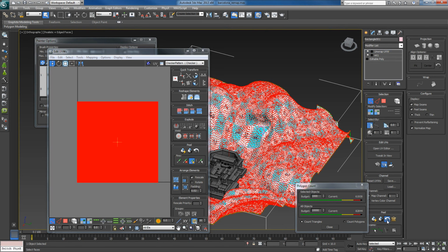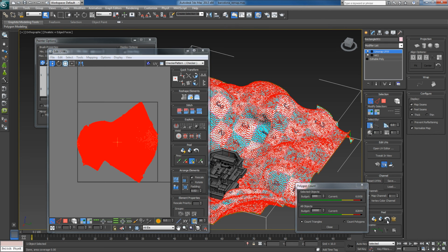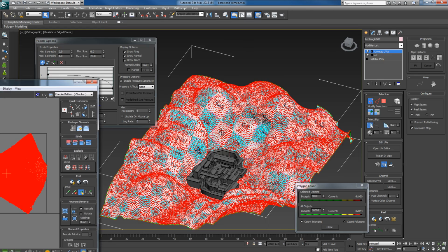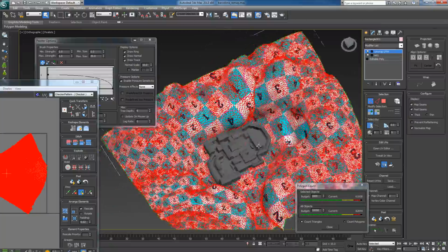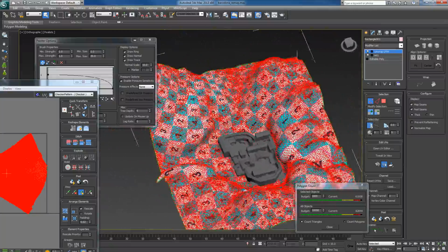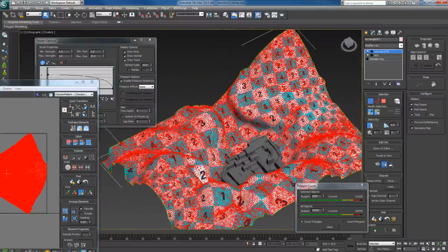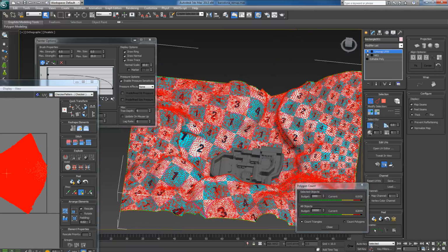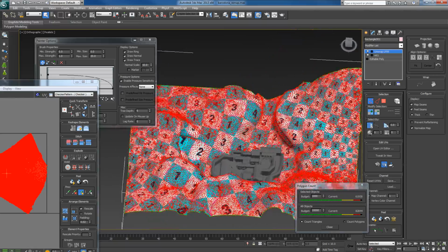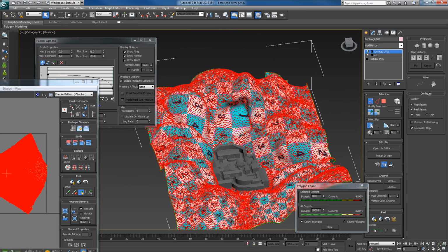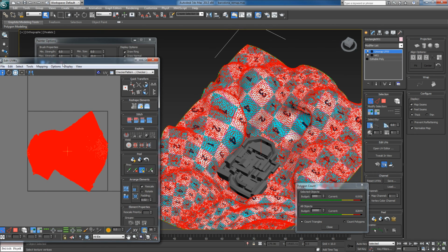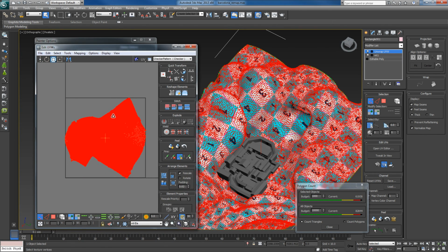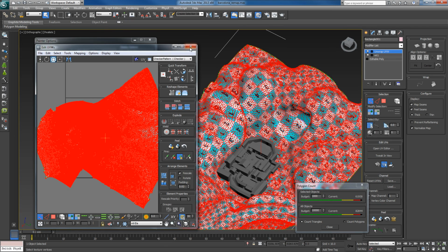Select all and do a reset peel, which should peel this out a little bit more like an orange would peel out. And our UV mapping should be a little bit better or superior to what we had as to overall detail. So yeah, you can see that everything is kind of normalized, in that one-to-one zone. We have some big areas and some small areas, so brushing on is definitely a lot larger in this area. So there's going to be some inconsistency as we paint textures and material onto that in a 3D plane. Let's pump things up a bit and cheat.